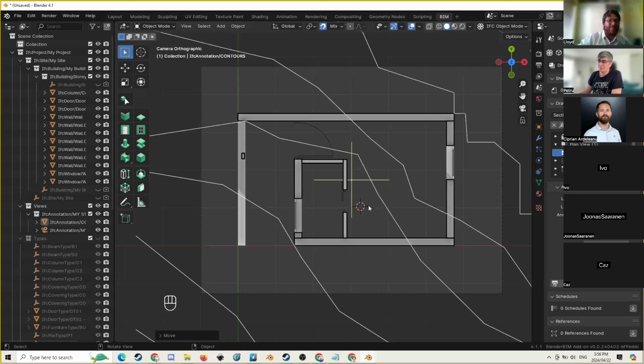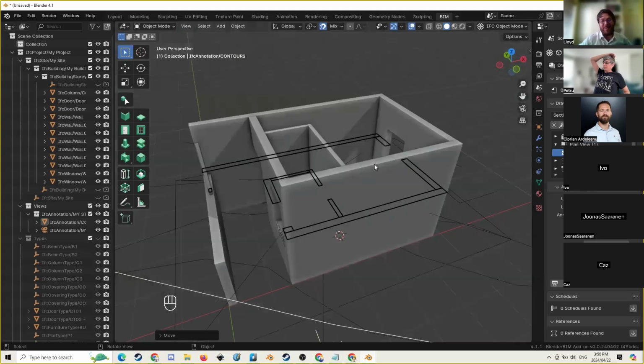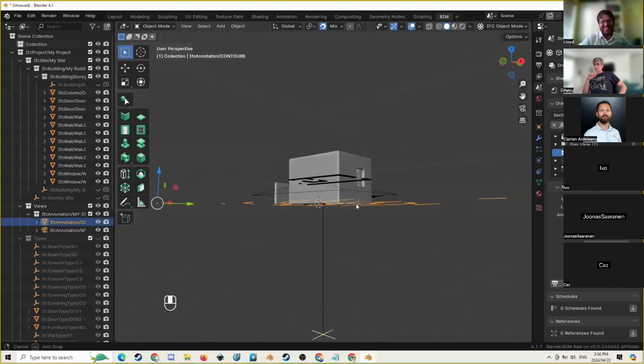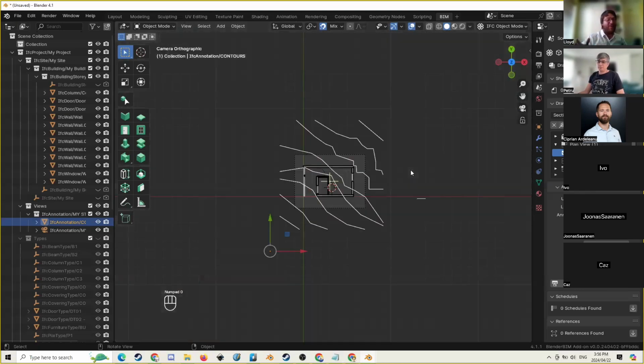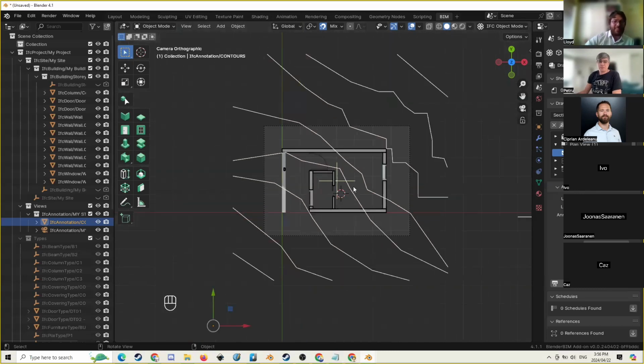Absolutely. And if you have an actual surveyor's CAD file with height information and all of that, because this is just fake 2D as a showcase, that would be a simpler way. But even inside of that, it would be quite complicated to bring that information in without saving it separately. Because if you wanted it to be stored inside of the IFC annotation, you're looking at contours as one example. You're looking at boundary elements, pegs, trees, foliage, water streams, stormwater. There are all these layers. It's still quite a slow process.